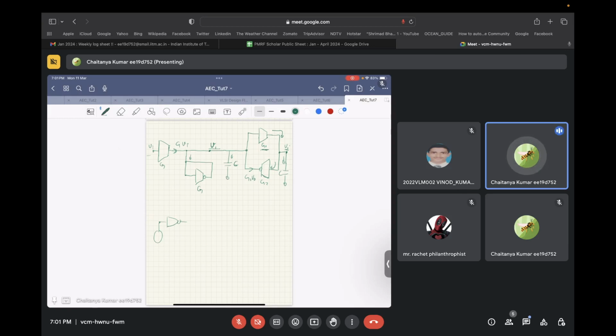So if that is the case, how will it behave? Let's consider this for now. This is the small signal input. This is basically equal to the self-biasing voltage. I have VDD over here, I have ground over here, and over here, let's say I somehow give the self-bias voltage using an inductor, and I take the output over here using a capacitor.